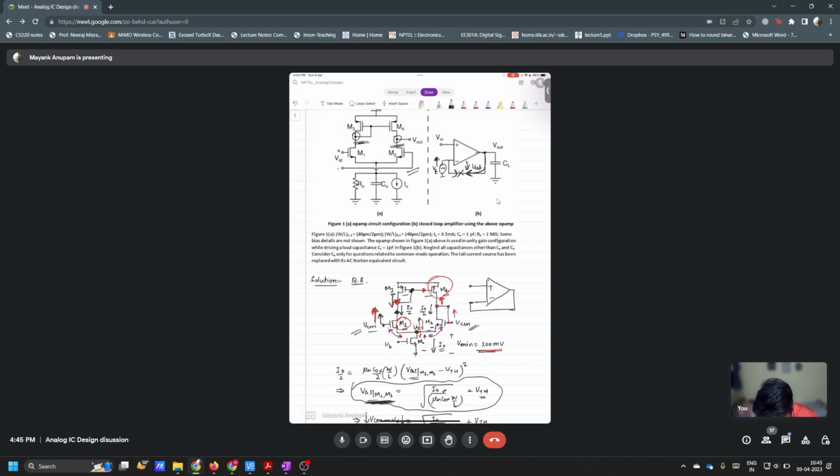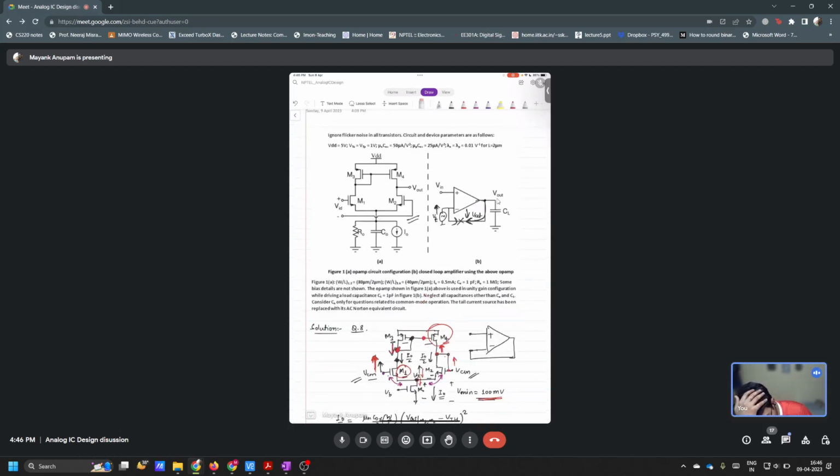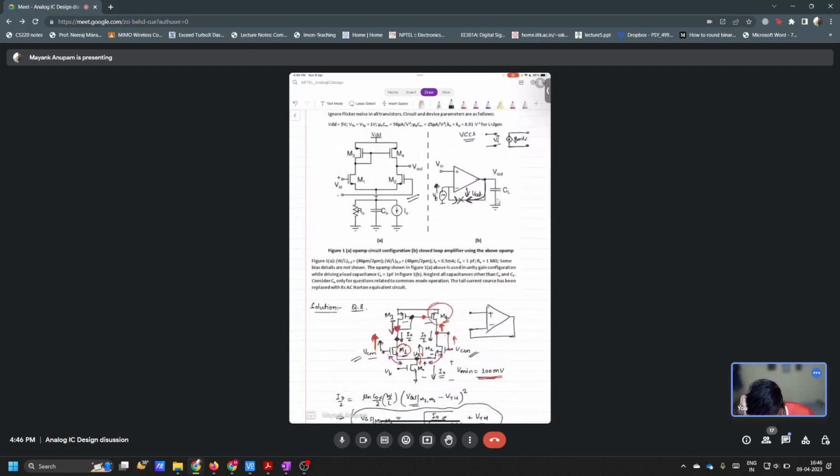We want to realize not an op amp but an OTA, a voltage controlled current source, a VCCS, right? And what is a VCCS? Symbol wise, you have a voltage between these two terminals, and you have a current here. So this is, let's say, Vi, and this is GM times Vi. This is what we want to realize, correct? Right.